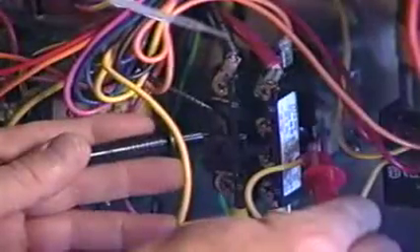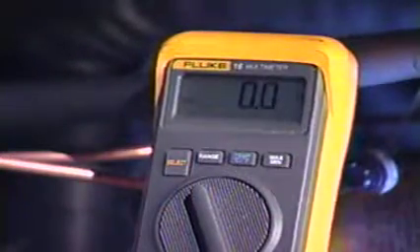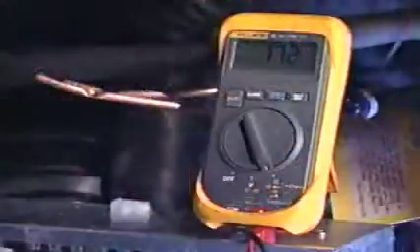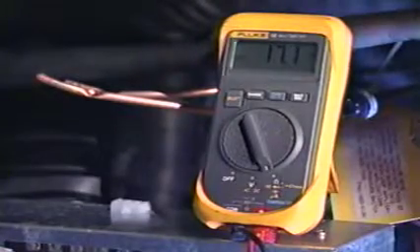Some coils, such as those on a potential relay, have very high resistances, so the proper resistance scale should be used. If the resistance reading through the coil is 0 ohms, the coil is shorted and must be replaced. If there is a measurable resistance in the coil of the contactor, chances are that the coil is good.